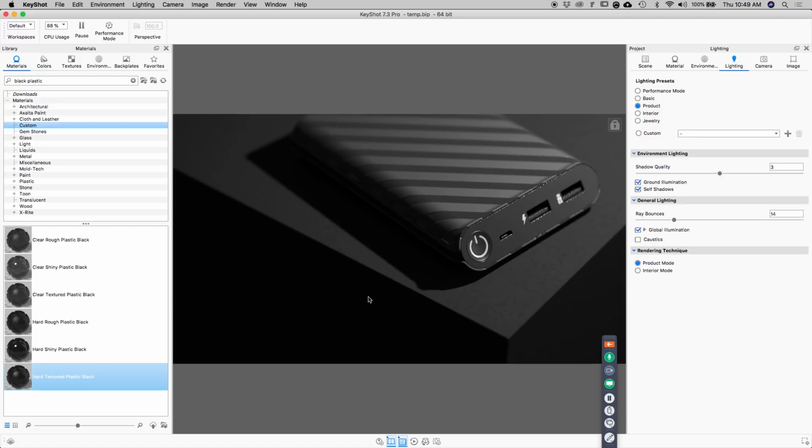This is going to set your real-time sampling to behave this way. For this scene, I certainly don't need 14 ray bounces, so I can drop this to like, I don't know, about 5. That will certainly speed up this rendering. You need a ray bounce every time light moves through a transparent surface. So in this case, I don't need very many. Just having a few helps the scene not get too many like black areas, so to speak.